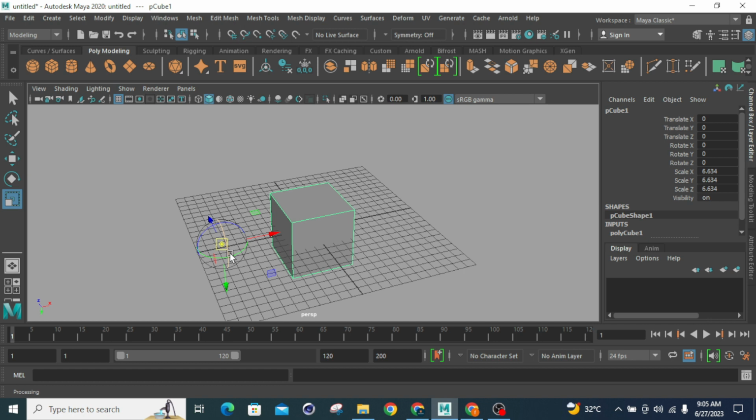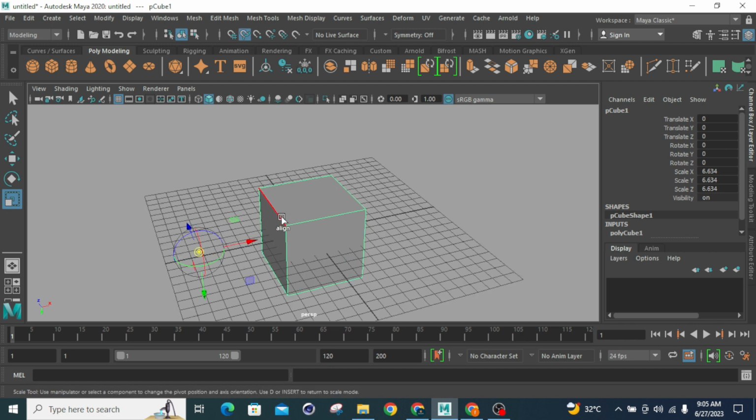Now you can see that when I use this command, this vertex point, which is basically a sphere in this orientation, will change into a circular shape. After changing into a circular shape, in snap to vertex you have to drag and drop. But in snap to edge, you have to click the C button and then use the middle button. This is my middle button. So you can allocate the point where you want. If I want my point here, I will click here.